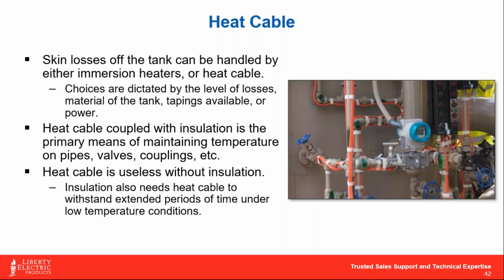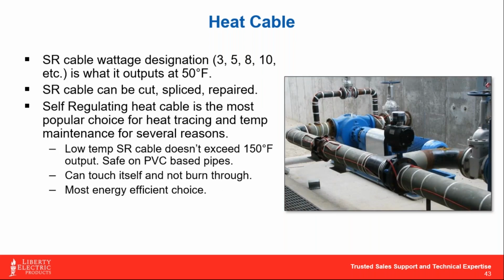Keep in mind that heat cables generally cannot offer up enough heat to actually transfer heat through the pipe itself and affect anything within it. Okay, so it's oftentimes a misconception that we're adding heat or can add heat to the process with a heat cable. When you're talking about Schedule 40 or Schedule 80 pipe, it's not going to happen. Especially once you put a flow rate behind it, you just don't have enough latency time for the fluid sitting in the pipe generally to affect its temperature change. So again, it's really just a means to offset losses off the system.